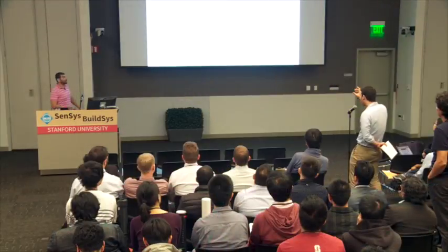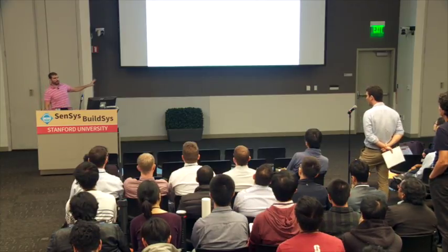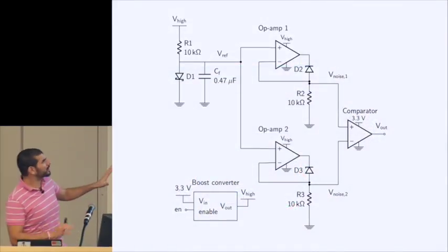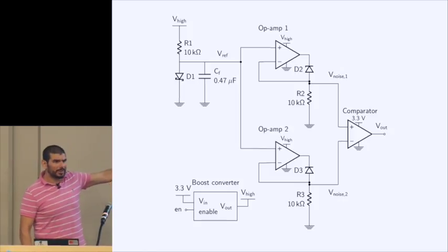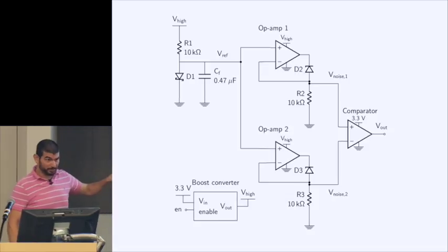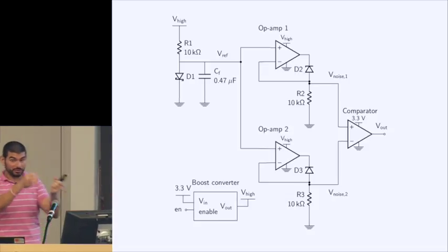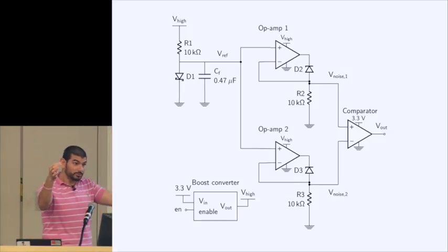So, like, if those resistors are not exactly the same, or those OTAs are not exactly the same, then you're going to have like a... Well, the op-amps probably we're not so worried, right? I mean, okay, if there's offset in the op-amps, maybe we wrap an integrator around it instead, life is okay. Resistor matching, I think, is always going to be an issue. Like somehow, when we're talking about matching, at the end of the day, we have to be able to come back to one component and say X equals Y, right?